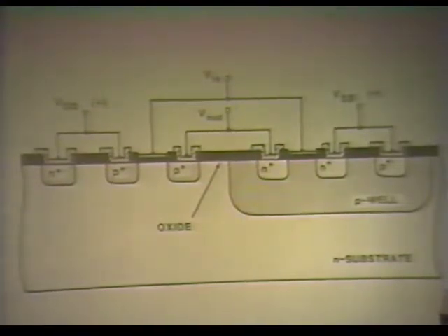And so that's why you build most of your devices on EPI, because with a few little tricks of putting it on EPI and a few other things, you can keep that SCR, which we call parasitic bipolars, because they're not important to the operation of the CMOS circuit. If you can kill those parasitic bipolars, you can keep it from going into latch-up.